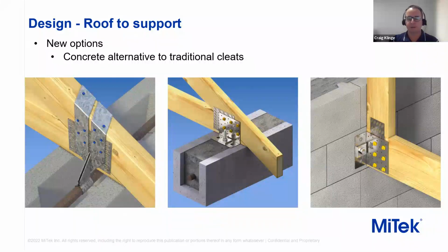For those that might be up in North Queensland or regularly deal with concrete block structures, there are various options aside from the traditional cleat options. So block flat or strap options, which will still hook into your bond beam, and then can be installed with either clouts or pneumatic nailing, or move into actually chem set screw fit brackets, which remove the errors of the cleats and reduce the fixing with the truss, in regards to having to drill out your M12 and M16 bolts through the cleat.